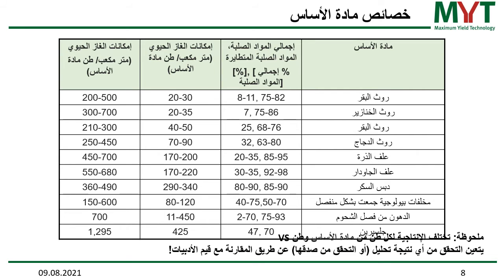That's why first to look at the biogas potential in relation to the tonnage of a substrate, wet mass, is a very good idea. Second, of course, the specific gas potential is important, because this tells you how easily degradable the target substance in the substrate is.